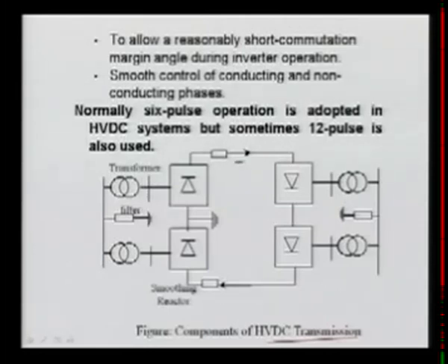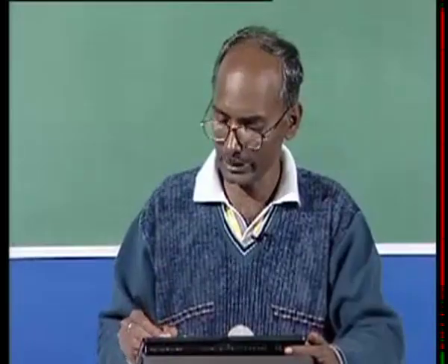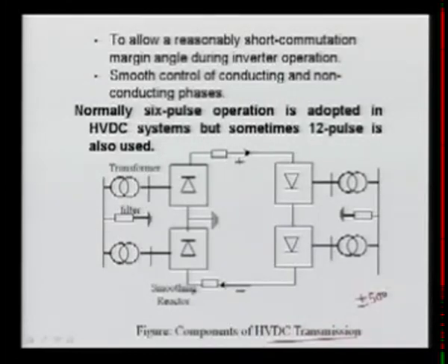Normally let us take it as plus here and minus here, and normally in the bipolar, the voltage is written as plus minus the voltage of one pole. Let us suppose I have written 500 kV. It shows that here it is 500 kV with respect to ground, and here it is also 500 kV with the negative sign. So plus minus is shown for bipolar operation.